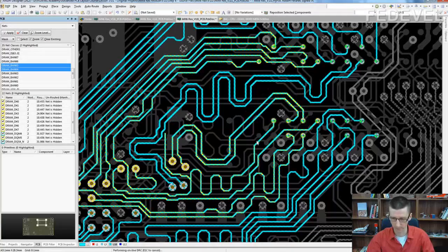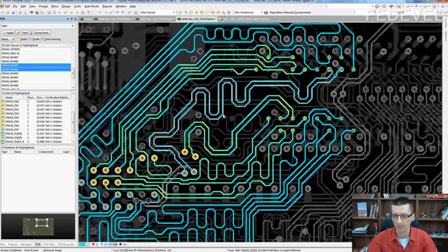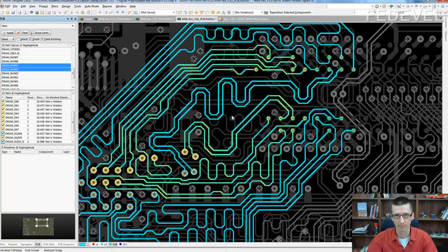See? If I delete this, we need 1, 2, 3. That's how we will save space when these two differential pairs are routed together. And it's important in some cases when your layout is really packed, then saving space from this big gap can help you a lot.